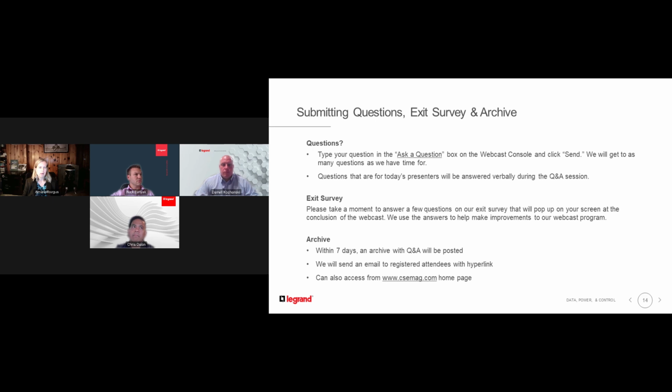Yeah, it varies by ampacity that you're selecting on the busway. Our 1200 amp, I believe, is rated up to 65K or 75kA. And then we have ways of doing fused end feeds too. So if you have available fault currents that are higher than what the busway is rated for, we can consider putting in fuses as well to help mitigate some of that. But it does vary on ampacity. So the general answer, it depends.